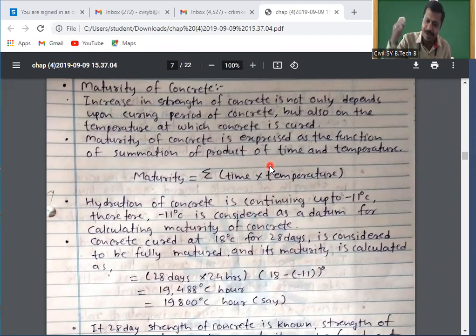Because with the help of that air conditioning system, you can maintain the required temperature. That is a very essential part for the concrete to cure, to gain the strength. Suppose you require a temperature range of 25 to 27 degrees. With the help of AC, you can maintain that. For the relative humidity that is required, again, you can maintain that with the help of the AC.